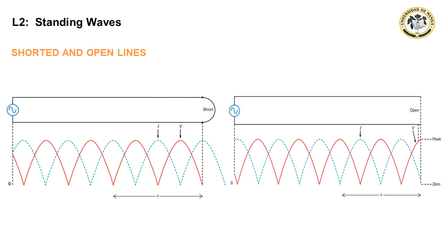Looking at the plot, you can see that the voltage and the current variations distribute themselves according to the signal wavelength. The fixed pattern, which is the result of a composite of the forward and reflected signals, repeats every half wavelength. The voltage and current levels at the generator are dependent on the signal wavelength and the line length. In other words, the effects of the reflected wave can simulate an open or short circuit at the generator.